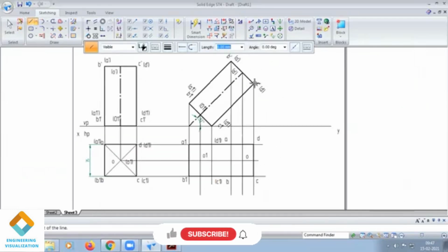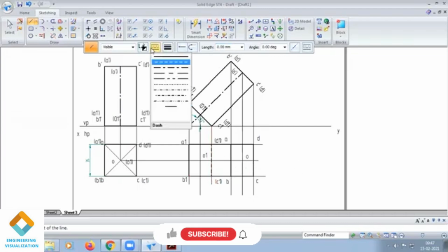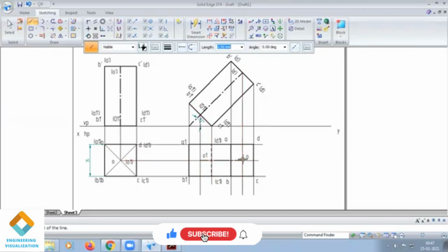Now visible face. This square face visible from the top view. Okay, that is ABCD is visible. Okay. Then this B dash, A dash, and B1 dash, A1 dash also visible already in rectangle. So this bottom face not visible from the top view. So we can write part of it with the dashed line. Okay, then finally we have an axis. So we can show the axis from A1 to O.